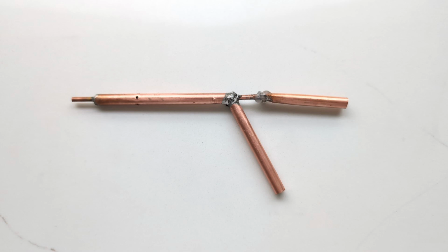So this is the fully constructed Pitot tube. The left side showing the dynamic input, the narrow tube going into the larger tube with the 4 holes around it, about 2 centimeters away from the end. And you have the two outputs, one the dynamic output which is going straight through, which has a junction between the small tube and the big tube, and then the bottom output is the one for the static pressure.